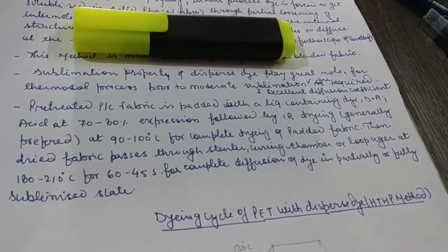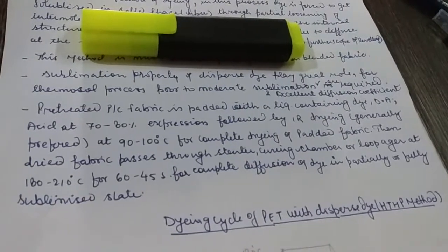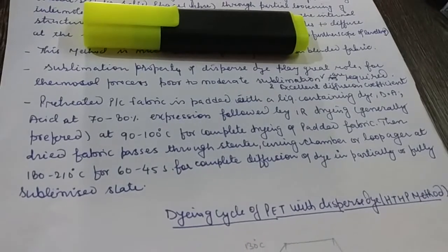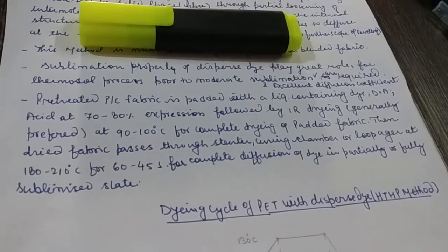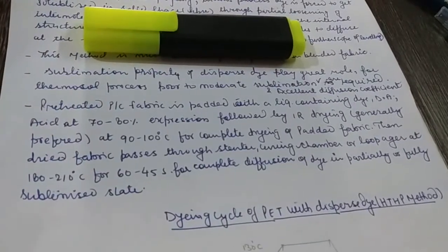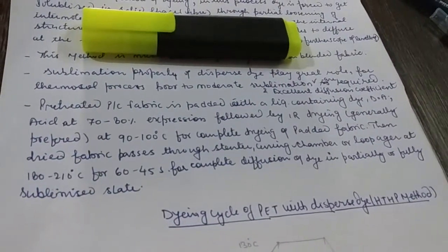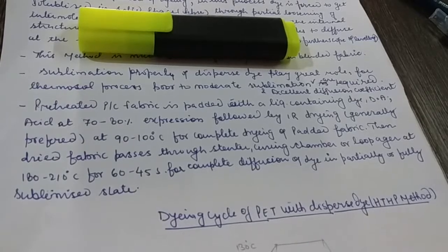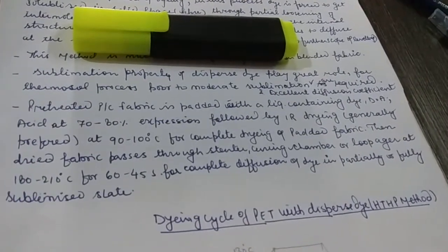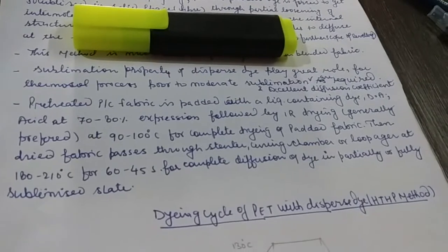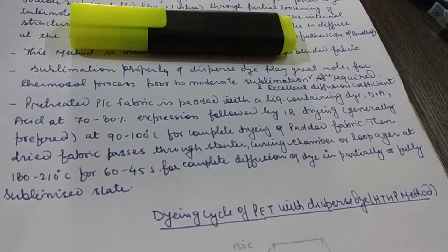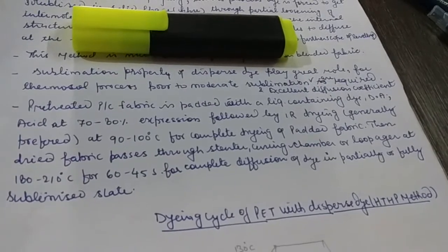During this process, we should avoid migration of the dye and ensure uniform deposition of the dispersed dye dispersion on the fabric surface. So we should place the IR heating system just after the nip of the padding mangle, so the passage after the nip to contact of heat on the fabric surface is minimum.